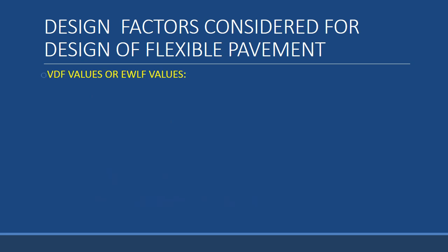So the next factor that we are going to consider is the VDF value or EWLF value. VDF stands for vehicle damage factor, and EWLF stands for equivalent wheel load factor, for which we have already solved a problem earlier in my previous lectures. Kindly go through it.